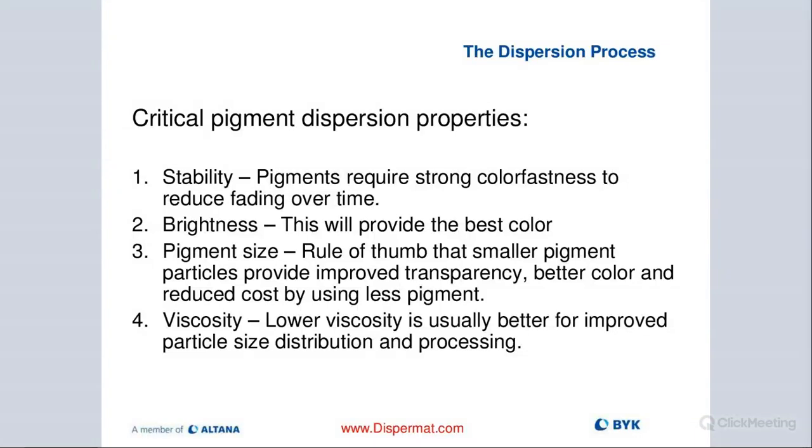So try to aim between 1 to 5,000 centipoise, and that would be giving us a really good viscosity range to process the material. But if you are higher, it's still okay. It just maybe requires some adjustments in terms of blade diameter and so on, as well as when we go lower, we also have to make some adjustments to make sure we can put in the right energy and we get a good dispersing effect.